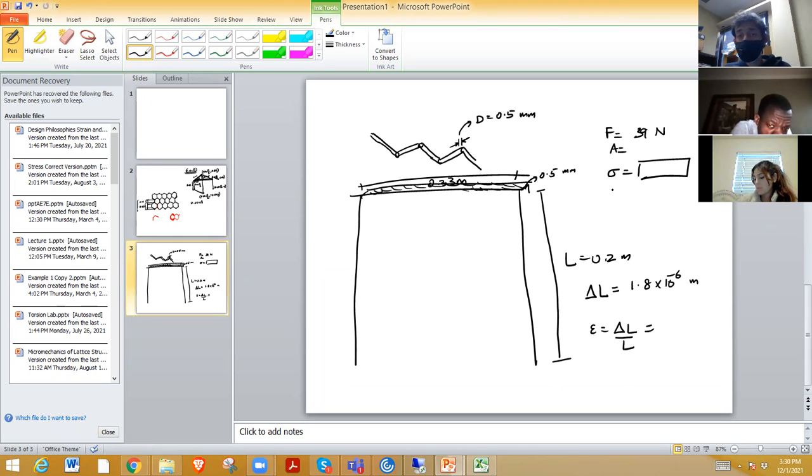So we got our strain, we have our stress. So effective elastic modulus is stress over strain, right? So now we got effective elastic modulus and Poisson's ratio. Those are the plane strain values E11 and nu12.